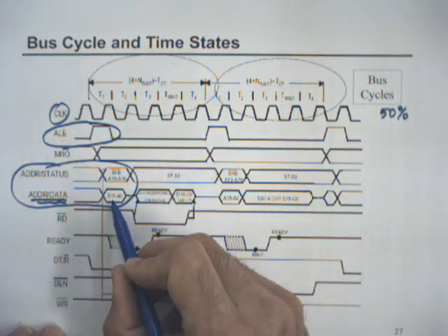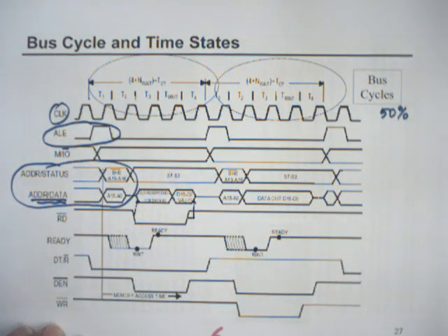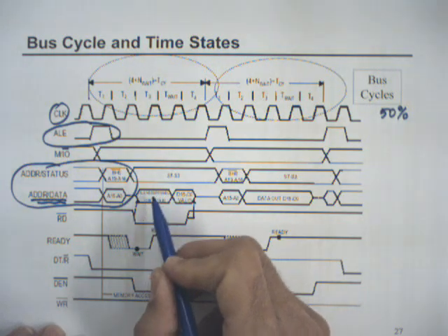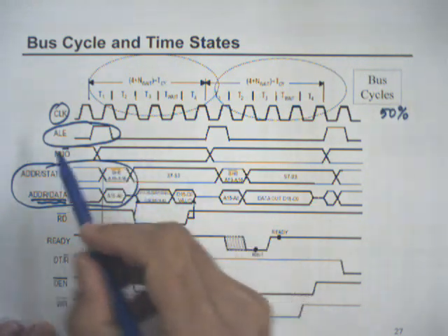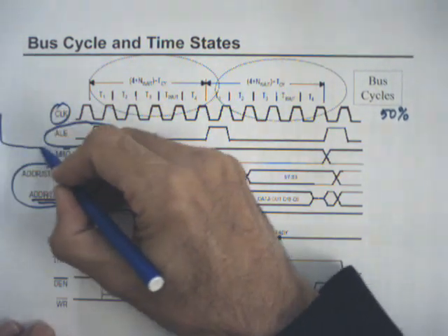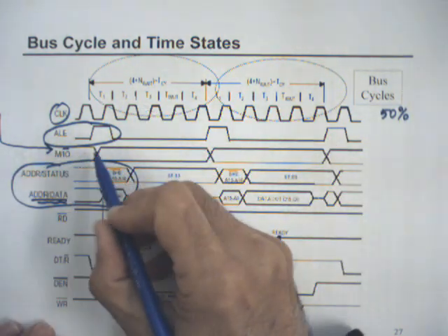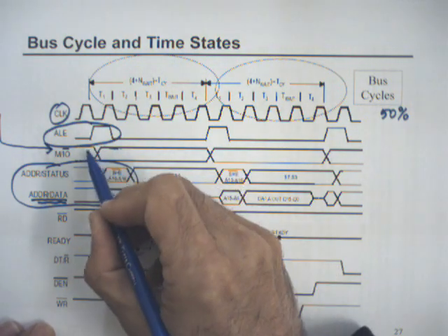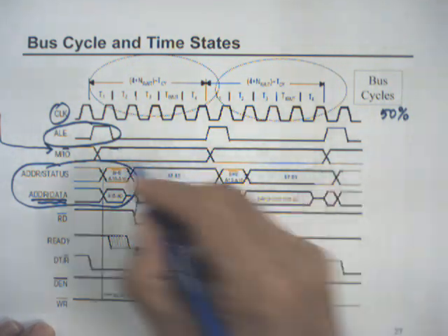Okay, so address 0 to address 15. So this is a 16-bit thing. 16 bits are multiplexed, and the other 5 addresses are or can be sent directly. So this is the first moment for address information. So the reason for address selection is either memory or input output. So if it's a memory, then it's 1 for memory selection. If it's I/O, it's 0 for I/O. So this is the compact figure for 2 options.